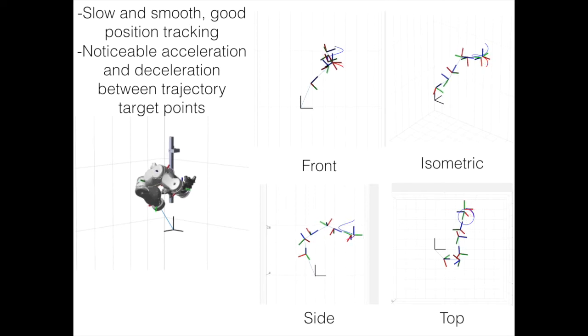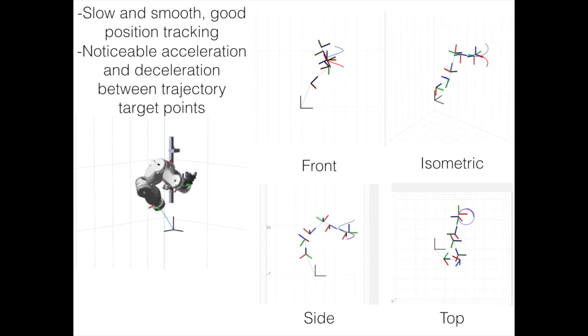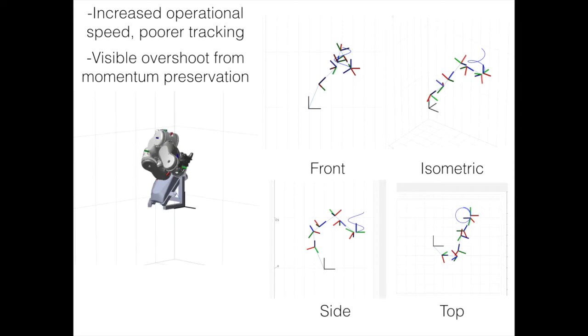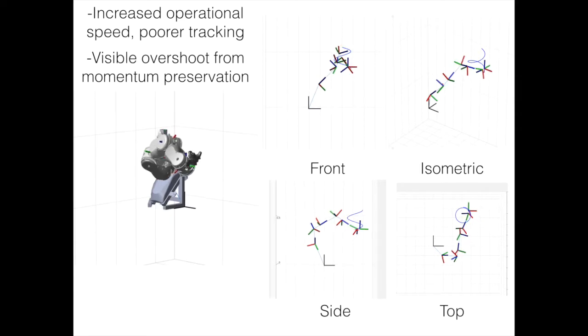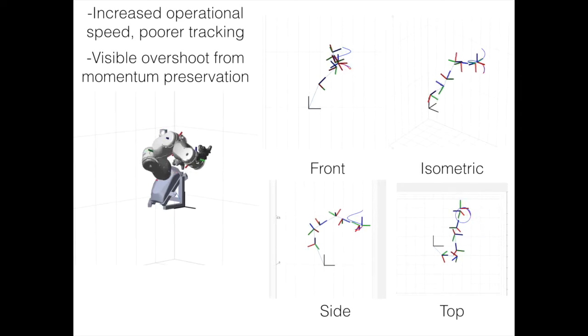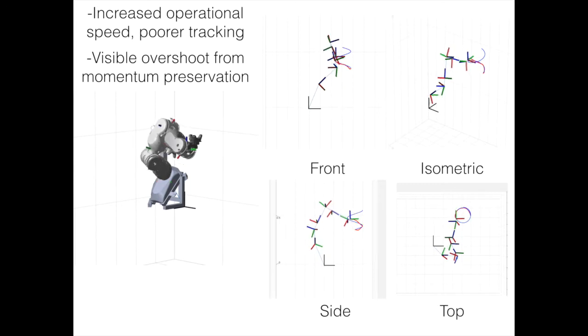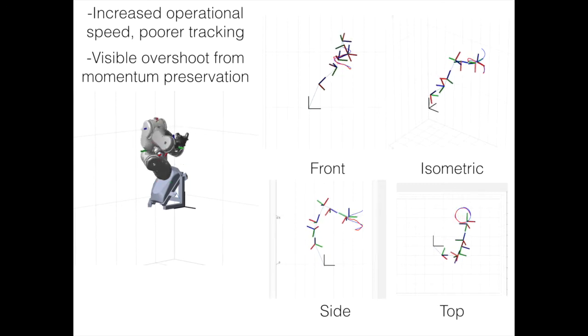There were some benefits to zeroing the velocity costs around the velocity from the previous time step. First, in our simulations the total time spent moving along the trajectory dropped, as expected, since the arm would move towards each trajectory point much faster. Second, the speed along the trajectory was also much smoother. This eliminated a previous problem where the arm would accelerate and decelerate between points in our pre-computed trajectory instead of just trying to smoothly travel between them.